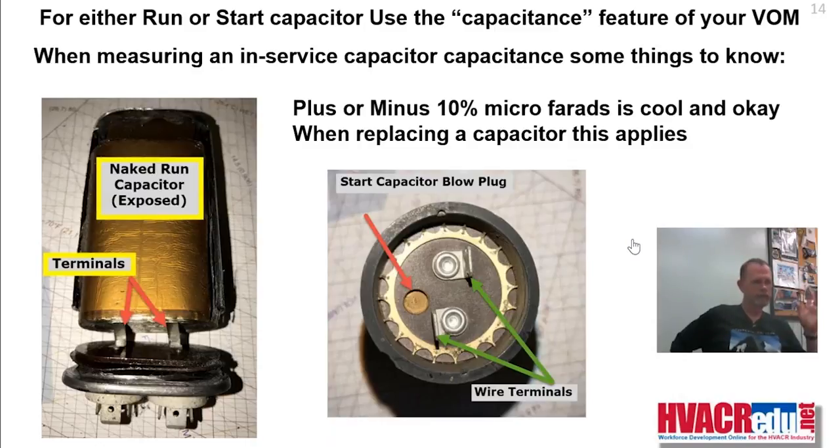Because of course, the start capacitors have a much higher microfarad rating, anywhere from 100 to 400, 500, 600 microfarads. That could smart a little bit if you got your little fingers across those terminals and it was charged. So, yes, it should have a bleed resistor in it. And the bleed resistor will keep you safe, but it will also keep the relay points from getting beat up so bad. Questions? Can I use a screwdriver?